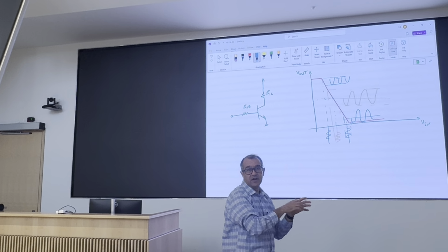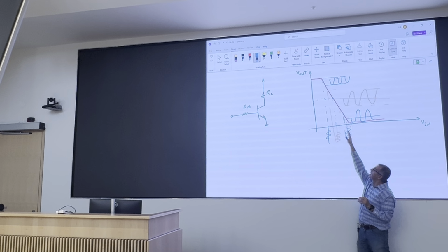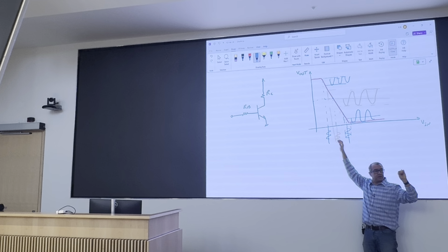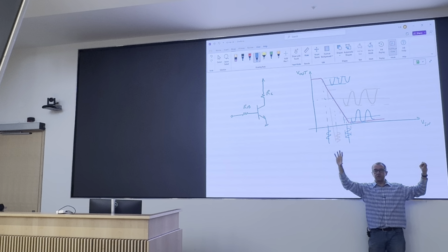But usually, if your amplifier is closer to these early stages in your chain of amplifiers, a lot of your signals from microphones are still small, condenser microphones, let's say. You want to go from 1 millivolt to 10 volts. You need a gain of 10,000, right? So distributed between 4 amplifiers, let's say each one is giving you a gain of 10.